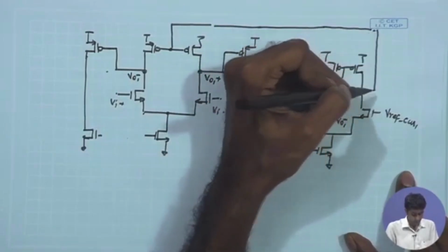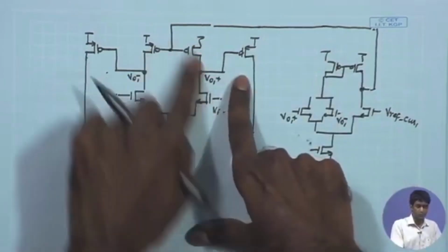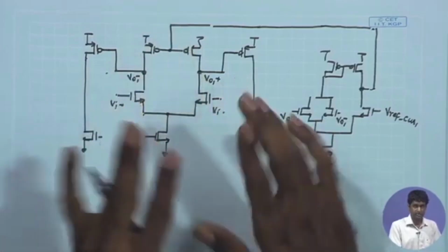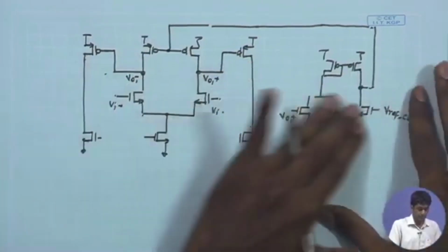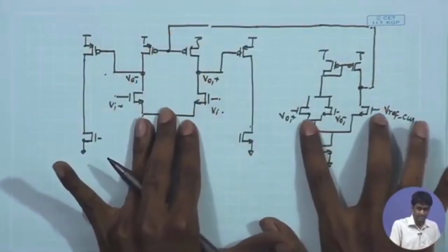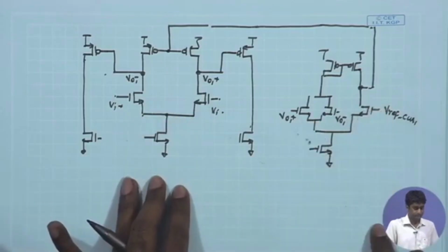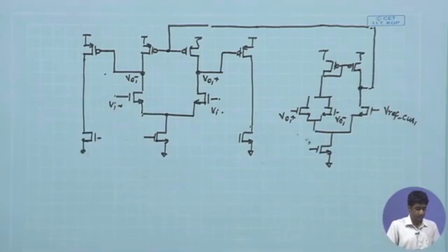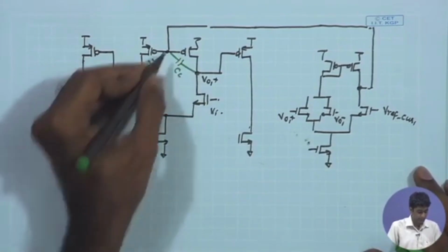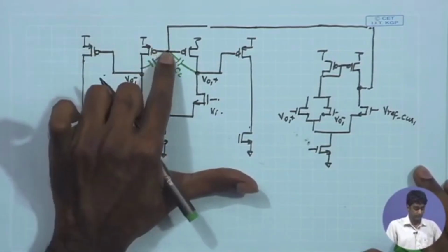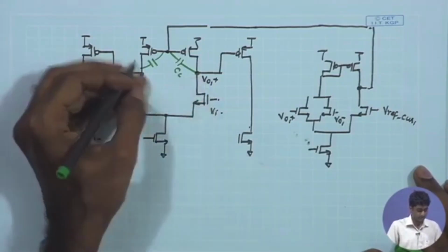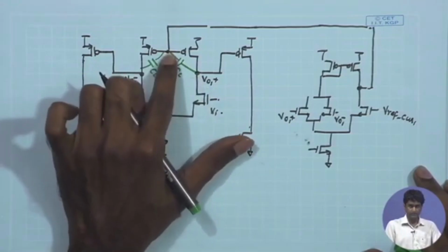And this is what we have done in the beginning while we looked into the common mode feedback of a single stage differential amplifier in isolation. So, we have already analyzed this particular configuration where you have the single stage diff amp compensated by an error amplifier, and we looked into the compensation scheme, and we suggested including coupling capacitors between the gate of the PMOS transistors and the output of the first stage, which is effectively going to give us overall mirror multiplication at this point.